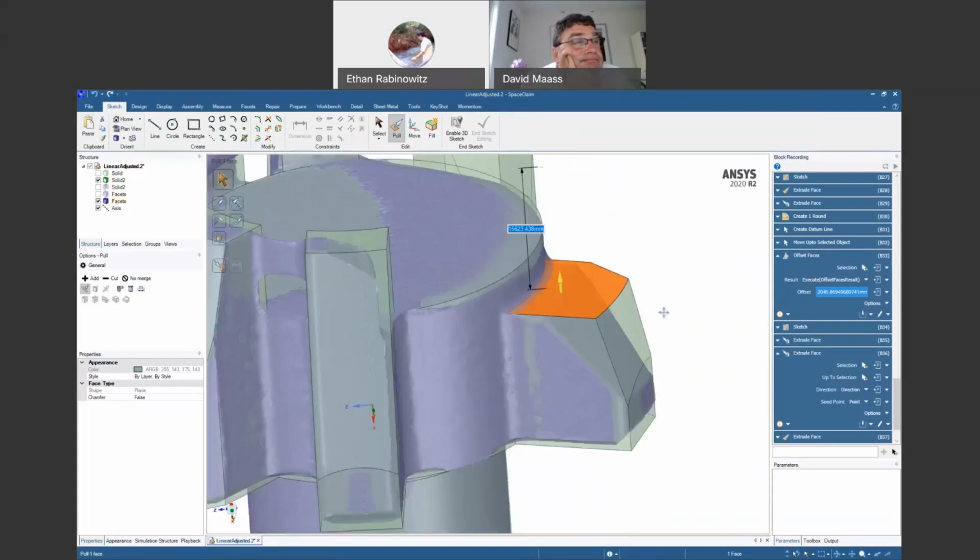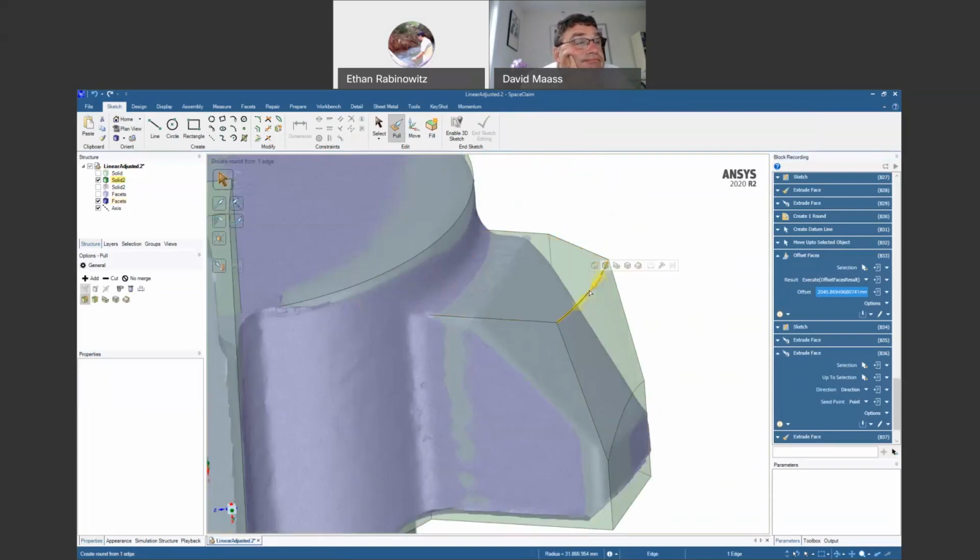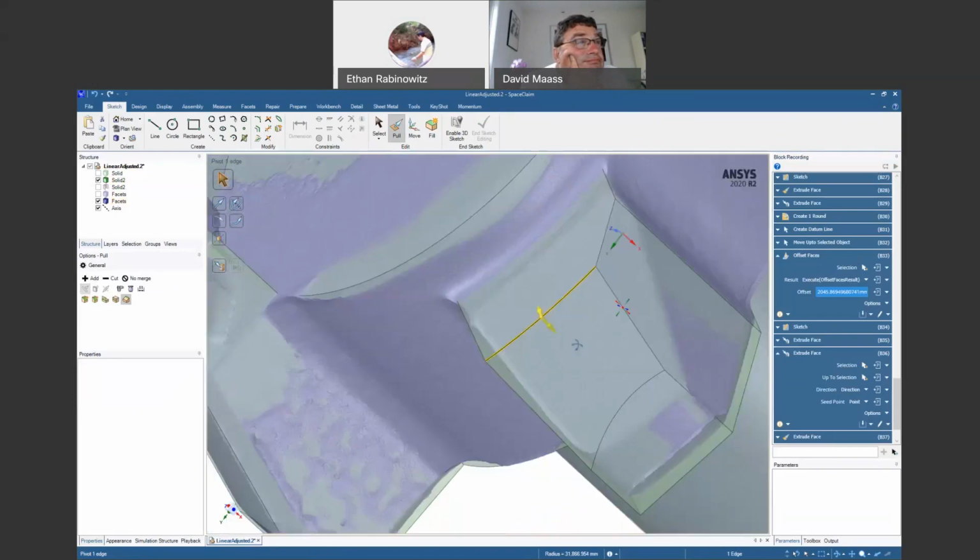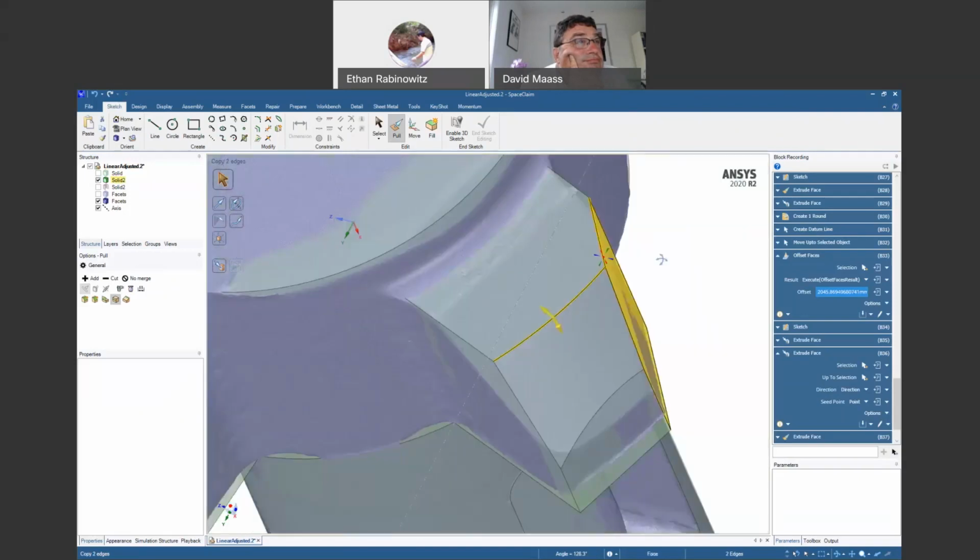That snaps like that. And then one way to deal with this edge, there's a few different ones. In the pull tool, if I pull on an edge, we create a round. But the last option here is called pivot edge. I could either pivot the edge downward, which is not what we want, so I'm going to escape that. I could switch to this arrow here. Hold on, is it this one? Let me see if I could grab both of these and do it.